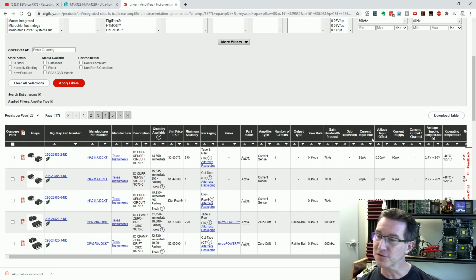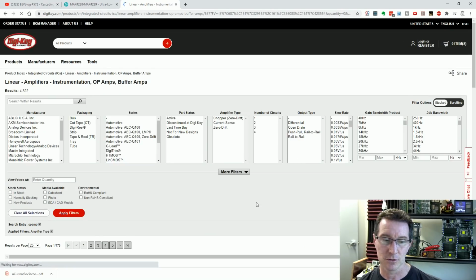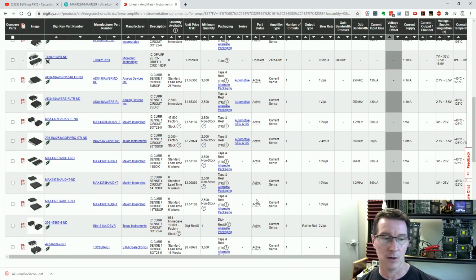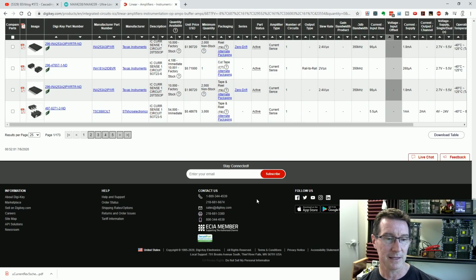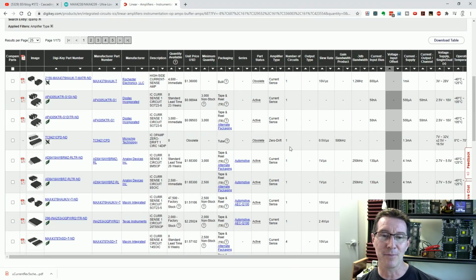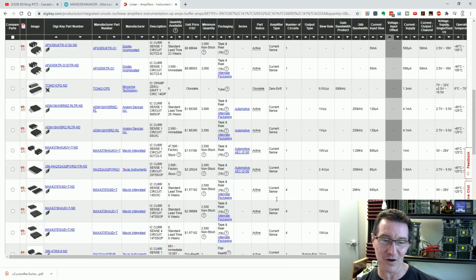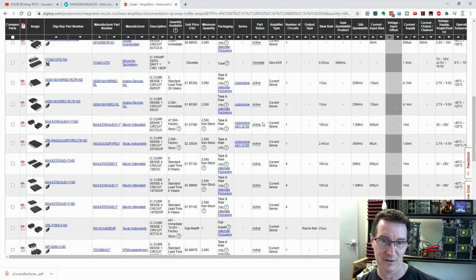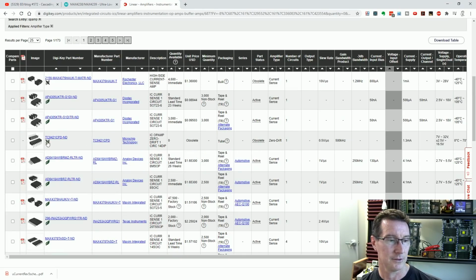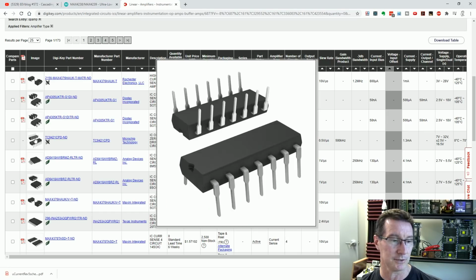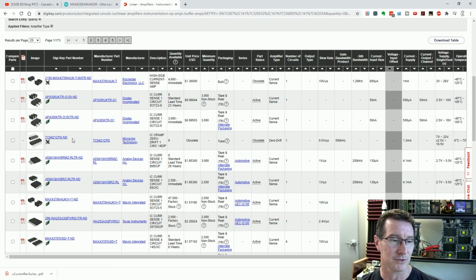All right, input offset voltage is the column that we want here. So let's sort from smallest upwards. Input offset voltage. Ta-da. Oh, we got some blankety blanks. Well, blankety blanks aren't going to help us, are they? That's really annoying. And these all happen to be the current sense amplifier type by the looks of it. No, it's zero drift. Too bad if you use that Microchip one. It's obsolete. Thank you very much. And DIP package. That's probably why. It's probably still got the same chip.